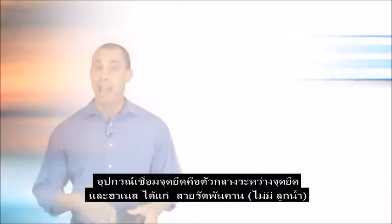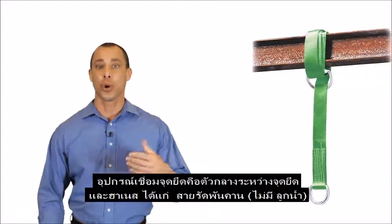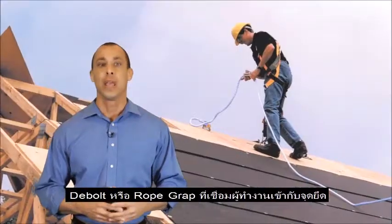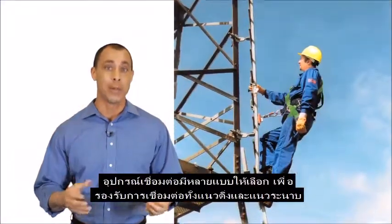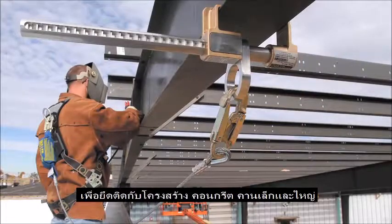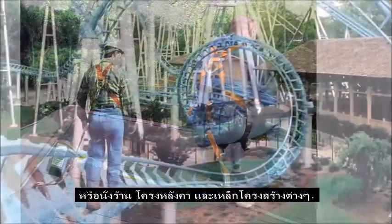possible. An anchorage connector is an intermediary fall protection device such as a cross-arm strap, D-bolt, or rope grab that links the worker to the anchor point. Anchorage connectors are offered in a variety of configurations to accommodate vertical or horizontal connections for attachment to concrete substrates, large and small beams or scaffolding, rooftops, and structural steel.